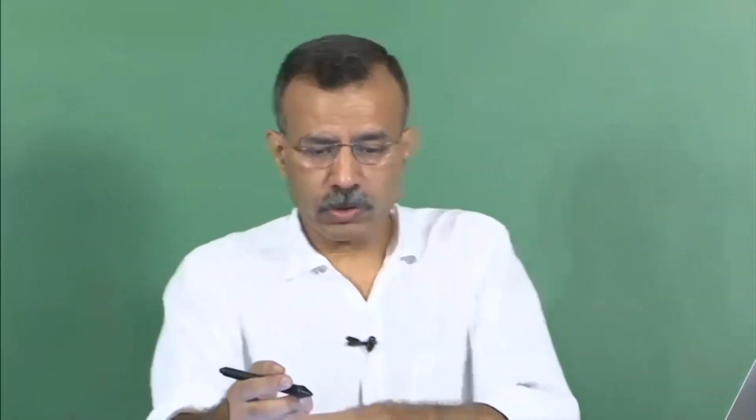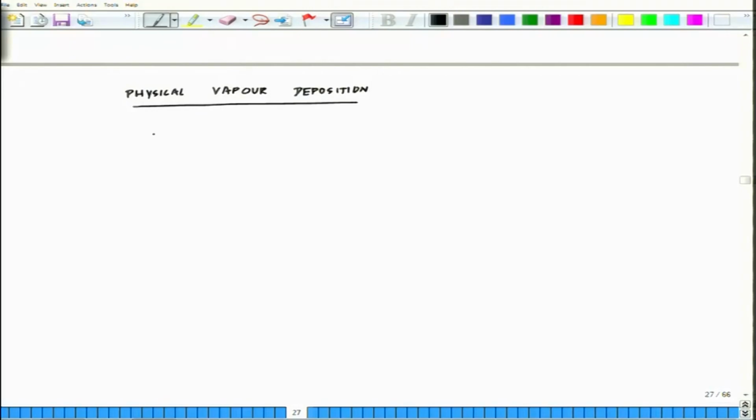Okay. So coming to the physical vapor deposition, which is also called PVD, it is an environmental friendly vacuum deposition technique consisting of three fundamental steps. So you realize that you need conditions of vacuum in such situation, and the first thing is vaporization of the material from a solid source. This is step 1.